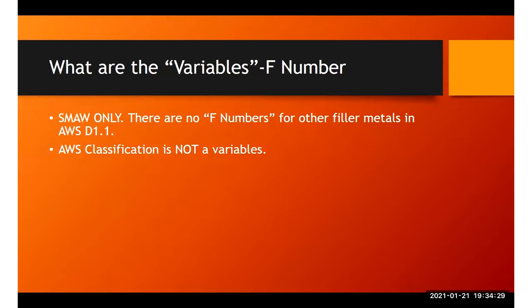Of course, the good part about that is this: if you were to take other codes as an example, ASME Section 9, for instance, all of the flux cored steel electrodes and all of the solid steel electrodes are all F number 6 anyway. They're all the same. It doesn't matter. It doesn't make a difference whether they're for regular carbon steel 70S6 or for high strength low alloy 100S1. They're all still the same F number anyway.